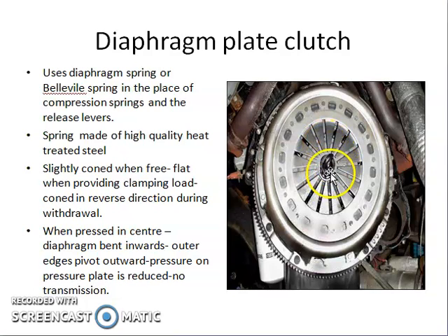These springs have spring-like slots and they are capable of flexing. When you press it in the center, the fingers just move upwards. When you give pressure in the center, the plate flexes inwards, or you have a reversed mode. So what happens? The force on the pressure plate is reduced. As a result, the friction plate moves away from the flywheel.